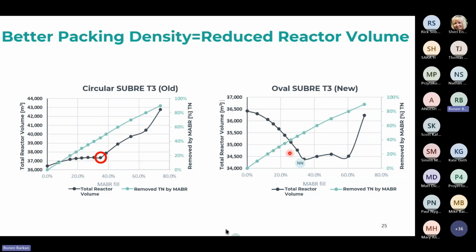One second, Ari, just to explain. Obviously, an MABR tower occupies a lot of the water column, a lot of the basin volume, right? So if you put in an MABR tower, you're basically taking a water volume that was going to be there. And so that's why you'd better compensate for it with the higher nitrification rate that you're getting with the MABR tower.